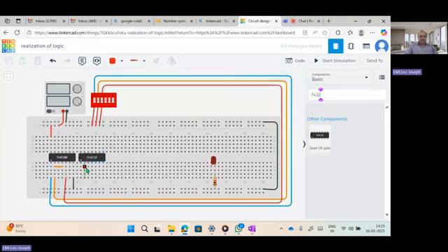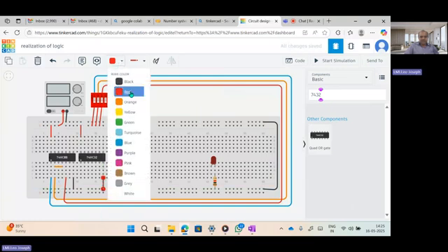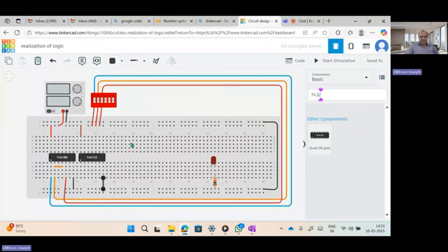So from here, same connection. From the top, I need to connect it to a power supply. Seventh pin should be connected to ground. Okay, and then this third pin is there. This is the third pin. 1, 2, 3 is the output. This third pin should be connected to first pin.